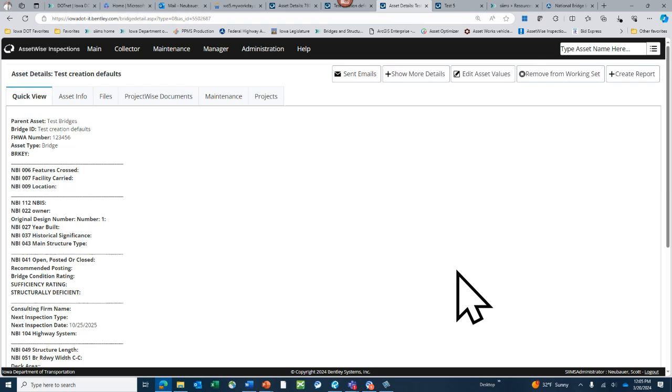We have a couple questions on the load rating. What if you use different rating methods for operating and inventory? For example, some steel I-beams with timber deck have the timber deck control the operating and the beam control the inventory. The steel I-beam would be load factor, and the timber deck would be allowable stress. Yep, it just depends on which one controls.